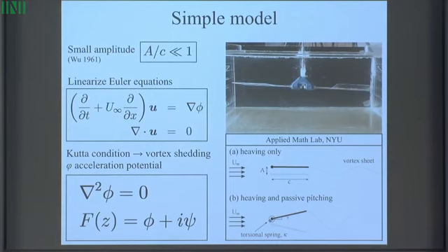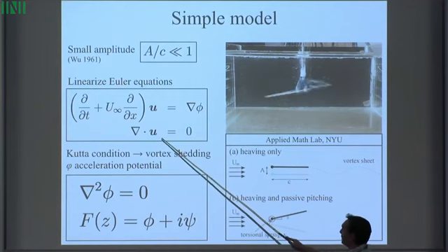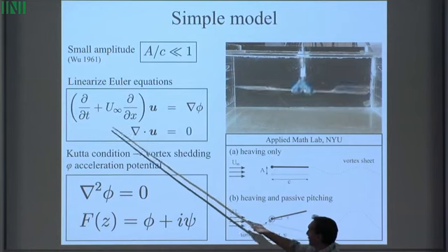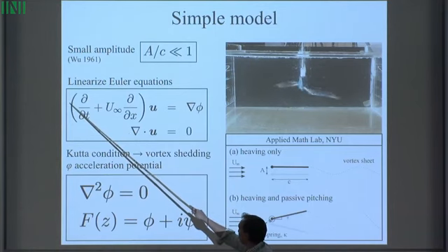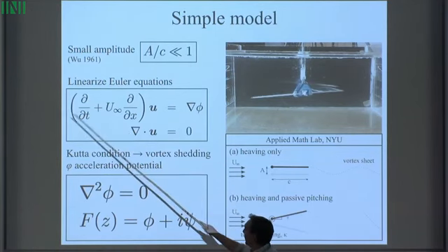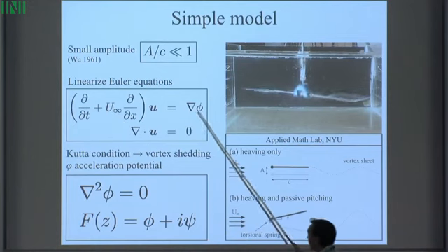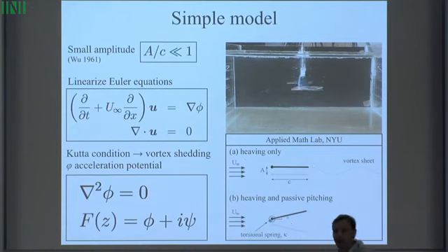So the nice thing is these equations are linear now. The flow is incompressible, so you could take the divergence of this top equation, and that divergence now commutes with this linear operator. So you get 0 on the right-hand side, which means that pressure is harmonic.